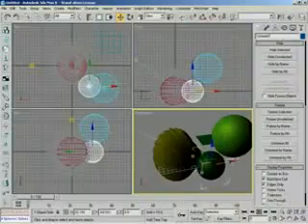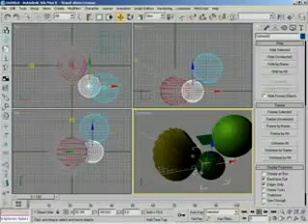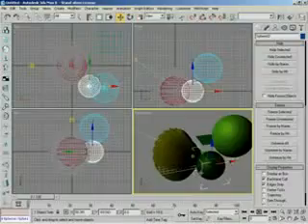So how handy is this? Well, what if you were working on a character and you started dealing with the creation of its control rig, and you're putting in bones and IK and helpers, but you don't want to accidentally select the character? Just freeze the character. It's that simple. Now you're done with the bones and you don't want to mess with those. Freeze the bones.